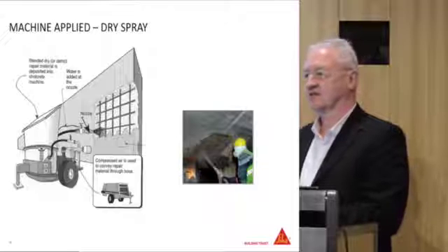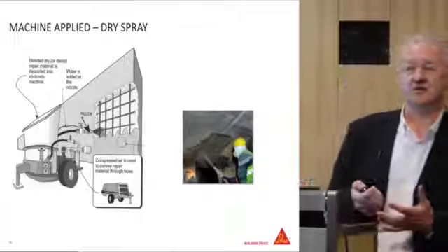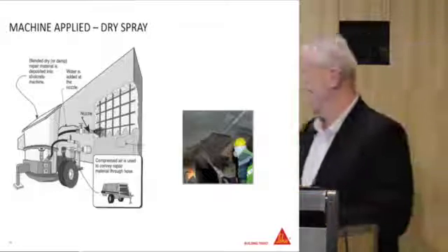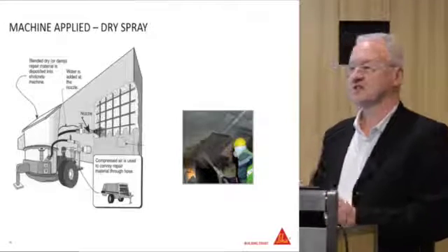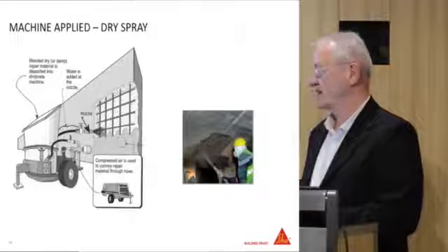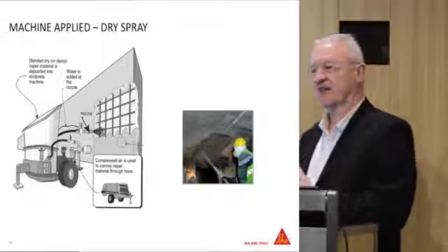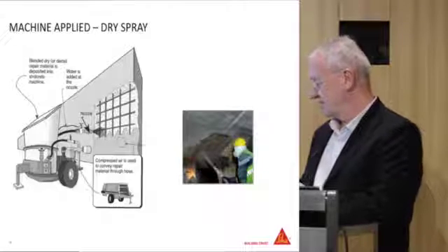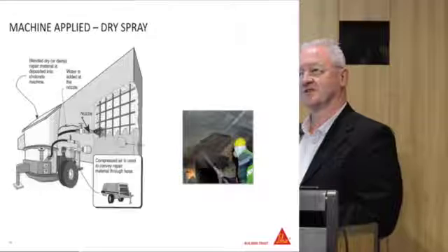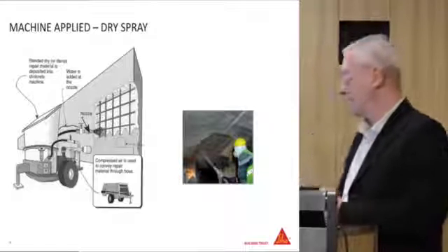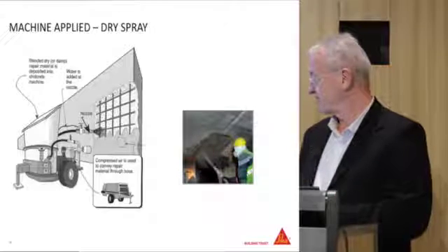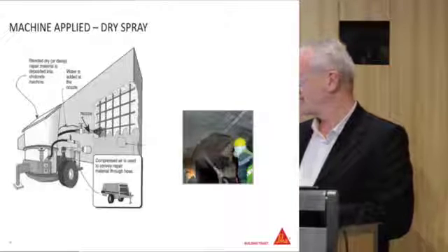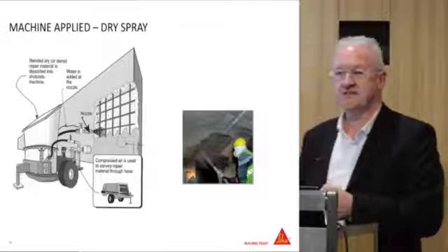And it's quite important from the point of view of the operator that he's qualified, and there is a certification for this. He'll apply the right amount of water to get the correct amount of build-up in the repair area, but he'll also have the technique to get behind the bars as well. And generally, you can normally judge a good, competent nozzle man, as we call them, when they start to work on the first part of the repair, because it should work on the bottom and gradually work up, and they tend to be quite active.